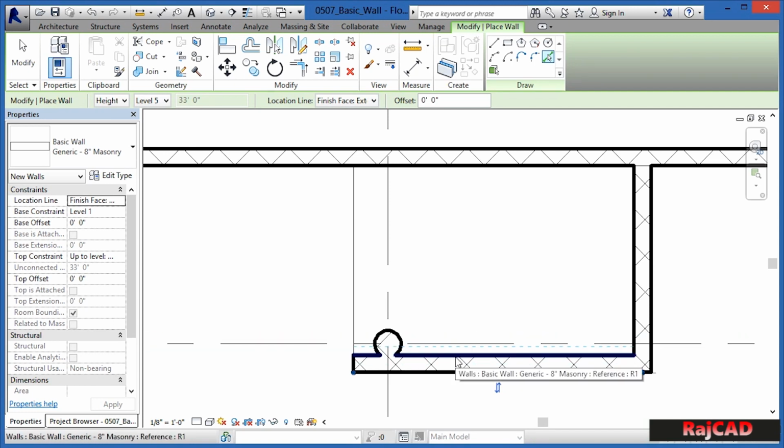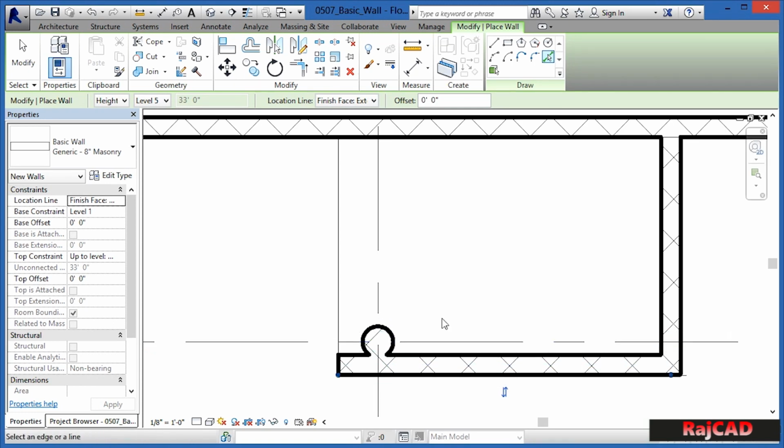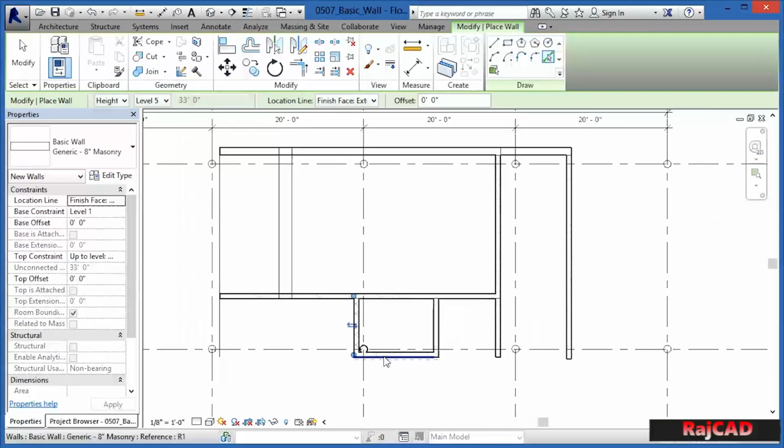Later on, this wall will get moved away from the column. And when it does, this column will automatically heal itself again, so it'll once again be perfectly round. For the next wall that we want to do, move your cursor up and make sure that the dashed line is toward the right this time of that line to place that wall in.